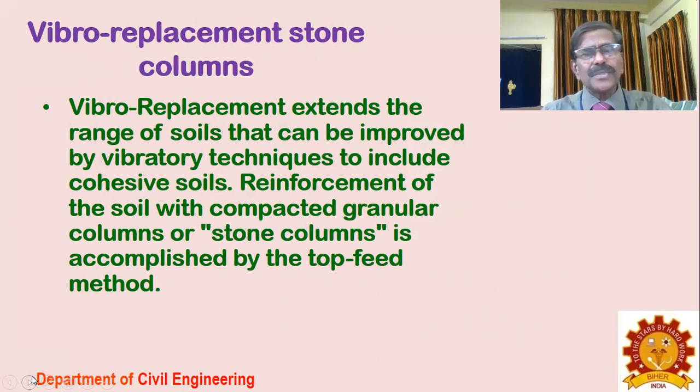So vibro replacement stone columns. Vibro replacement extends the range of the soil that can be improved by vibratory techniques to include cohesive soil, and reinforcement of the soil with compacted granular columns. And stone columns are accomplished by the top fed method. So you feed it with small granular stones, which cause the compaction to remain in its own place.